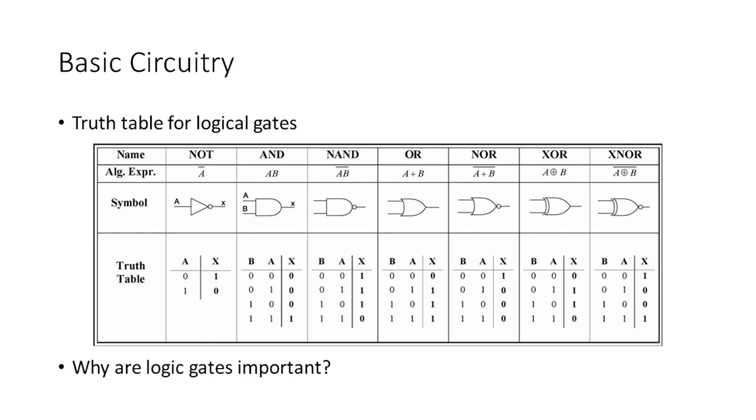For the AND, both input signals are required to be 1 in order for the logical unit to output a 1. This is inverted with the logical NOT AND, where whenever the inputs are both not 1, the resulting output is 1. For the OR, only one of the signals has to be 1 in order for the output to be 1. For the NOT OR, neither of the signals can be 1 in order for the output to be 1.